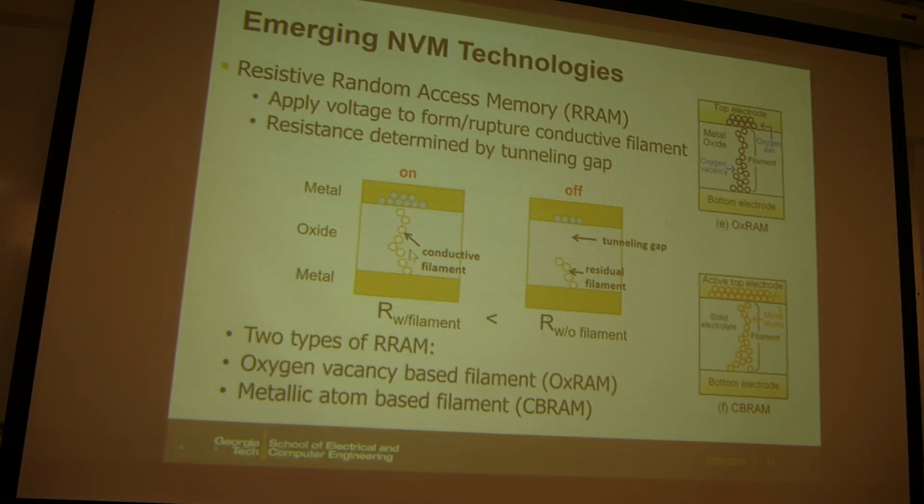So it's high resistance. But when you apply some voltage, when the oxide is very thin, like a few nanometers, you can break down the oxide. So basically you create many oxygen vacancies. You knock out the oxygen atoms from the oxide lattice, and then you create this filament based on the oxygen vacancies. And then the current can flow through the filament. So it's like a conduction path between two electrodes.